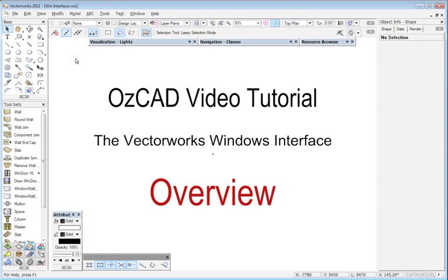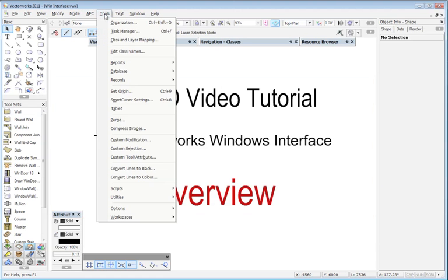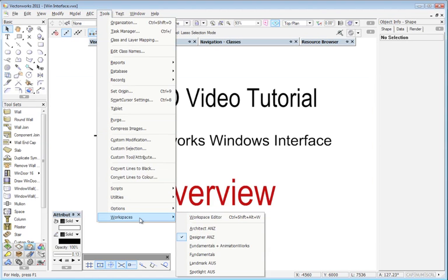I guess the first thing you're going to want to do when you launch Vectorworks is to make sure that you have the correct workspace or tools and menus available for the product that you've purchased. You can do this by going to the Tools menu, going down to Workspaces, and then checking that you have Architect, Designer, Fundamentals, Landmark, Spotlight, and so on.